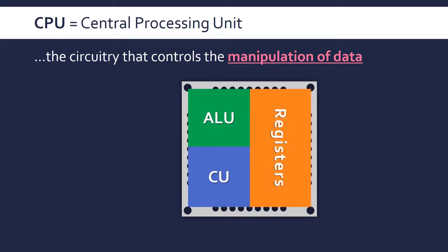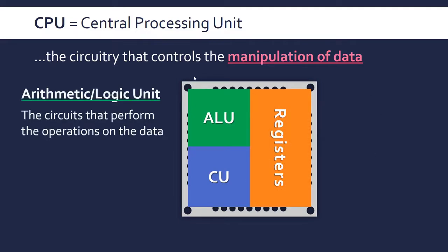and the register unit. So firstly, the CPU isn't obviously this simplified, but the ALU is actually what does the processing, that actually carries out the instructions. This is the arithmetic logic unit. It's written with a forward slash for some reason. I can't say I know why, but it is. So ALU, arithmetic logic unit, and this actually performs the operations. So it performs the arithmetic operations like addition, multiplication, division, and so on, and the logic ones like, basically evaluating something to false or true, the two Boolean values.